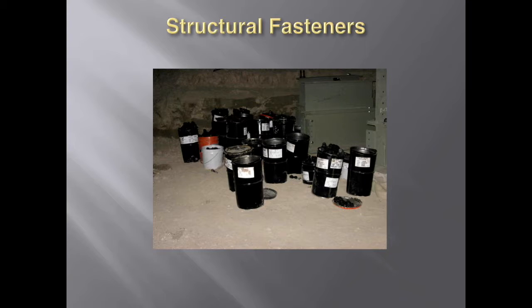Structural fasteners. In the submittals, they'll have a bolting procedure that's required to be submitted. One of the things in that bolting procedure they talk about is storage of bolts. As you can see here, it's pretty dusty on any of the construction sites. We deal with the dust. These bolts are all coated, and they actually have to have enough oil on them so that when you touch them, you get oily hands. They have to be oily to the touch.